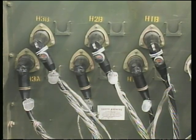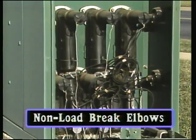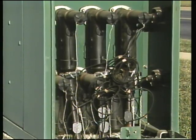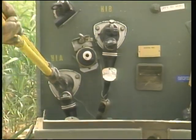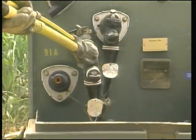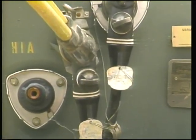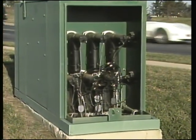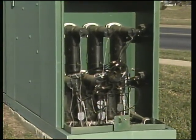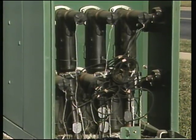There are two basic types of elbow terminations: load break elbows and non-load break or dead break elbows. From the outside, they look similar, but they're designed to work differently. Load break elbows are designed to interrupt the flow of current. They're typically used as switching points between cables and pieces of equipment. For example, a pad-mounted transformer can be de-energized by removing a load break elbow. The non-load break elbow, on the other hand, is designed to serve only as an insulated connection between a cable and a piece of equipment. It is not designed to be switched under load.